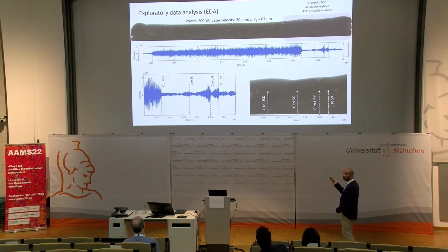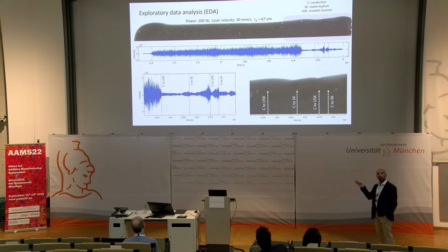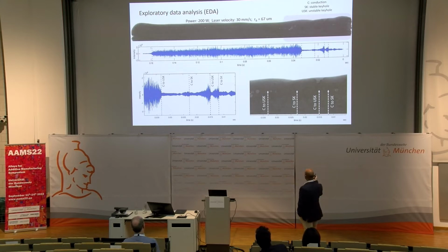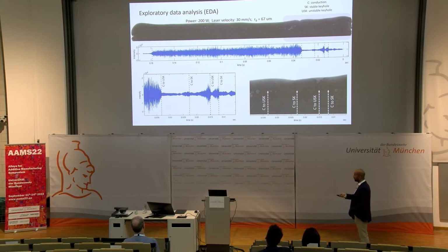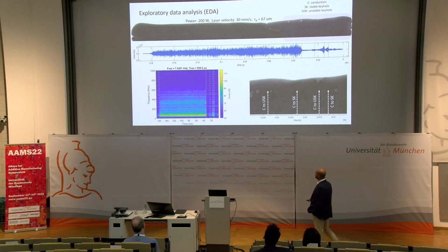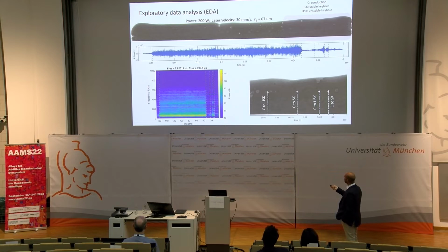And you can see clearly, just by looking at the raw data of this acoustic signal, that there's a clear correlation between the start of these regime changes and these instabilities and what we see in the time domain. Going to the time-frequency domain, or the spectrogram, you can see these events clearly present, elongated, of course, in the frequency.